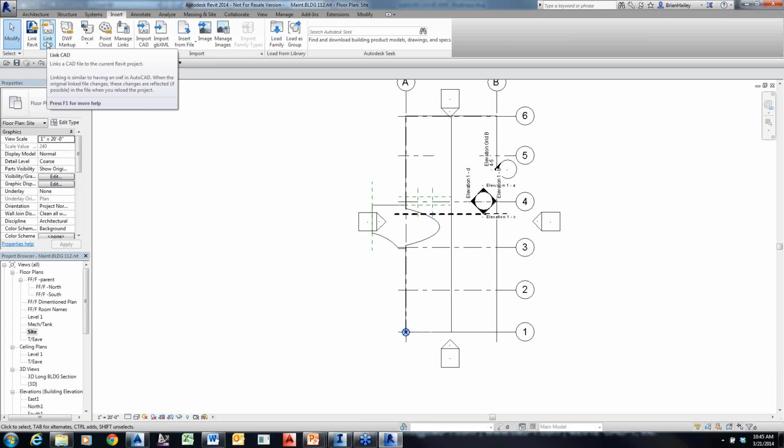So for those of you that use Civil 3D, you can imagine taking all of your triangles, creating points on those triangles, and then creating a surface from those points. That's what you're going to get in Revit. It does not honor the triangle edges. I always equate this to, in Revit, it just looks for the point and looks for the nearest points around itself and says, okay, we connect together. Exactly. Even if they don't in Civil 3D, Revit just interprets that as, hey, you're near me, let's hold hands. And that's kind of how the whole process works out. Yep, it is a pure Delaunay triangulation method with no alterations.